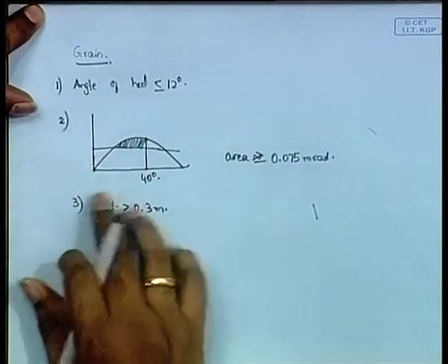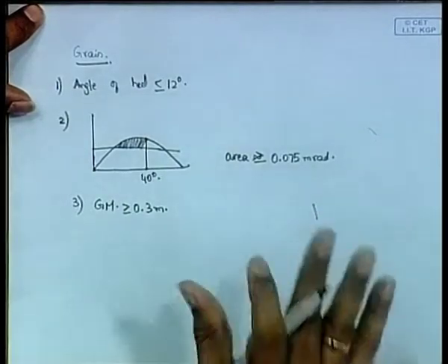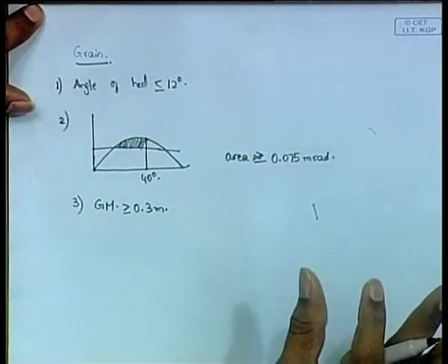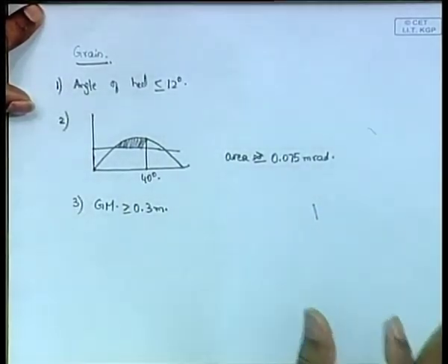In case you have such merchant ship conditions, the problem will state which rules you have to apply. The moment you see grains in some kind of container ships, you use these rules. The angle of heel, these three rules, all three have to be satisfied. The question will be whether the ship is stable or likely to be certified.